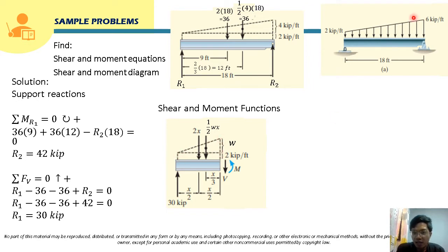And we know that the rectangular load, class, we divide this into a rectangle and a triangle, right? So the rectangular loading here will be just constant, so it will still be 2 kips per feet here. But for the triangular load, this is varying, so we don't know the value, or the height, of that triangle. So we just name it W here. We are going to solve for the value of this W later.